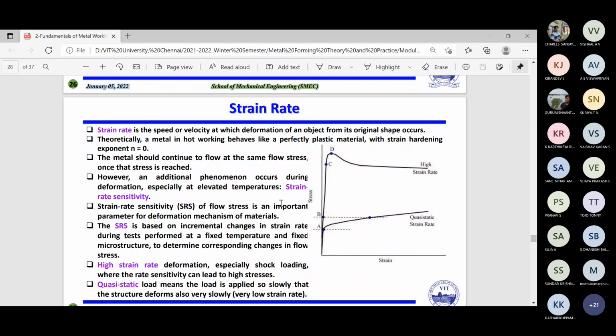But you have to hold it, because whenever you understand the heat treatment cycle, you have to go up to a certain limit. That means you have to increase your temperature up to a certain limit. Then you have to also think about the heating rate. You cannot think about just increasing maybe 10 degrees per minute or 2 degrees C per minute. That also will affect, but that depends upon the material.